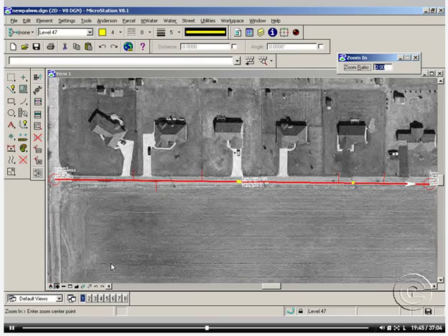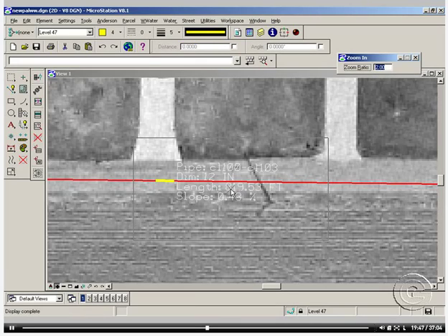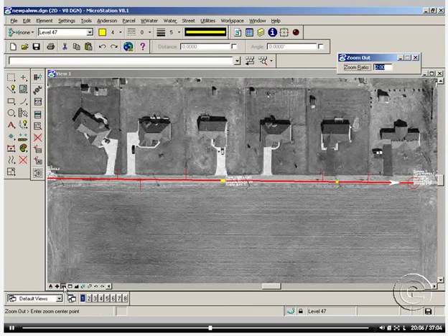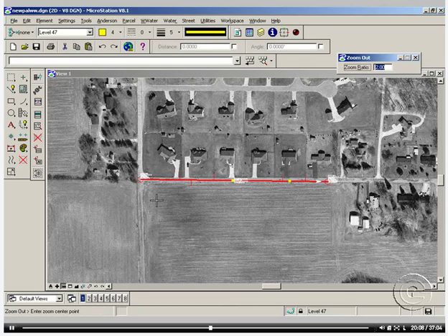And again, as you go back here, you would see that not only your map and graphic data is updated, but also everything in the database that is linked or related to that node is also updated, and that slope of that pipe now has changed from what it was before to the new slope. And as you can see, also the length of the pipe has changed also from its original value to the new value, which correspond to the new location of that node.